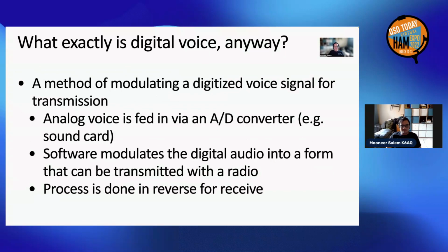What exactly is digital voice anyway? Well, in short, it's a method of modulating a digitized voice signal for transmission. And that consists of a few steps. First step is typically that your analog voice is fed into your computer or microcontroller via some sort of analog to digital converter. If it's your computer, that's typically your sound card. Next up, software on your computer or microcontroller modulates that digital audio into a form that can go back out over the air. And initially, that doesn't seem like it makes sense.